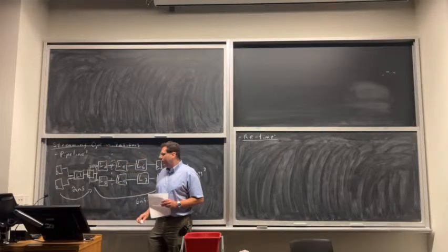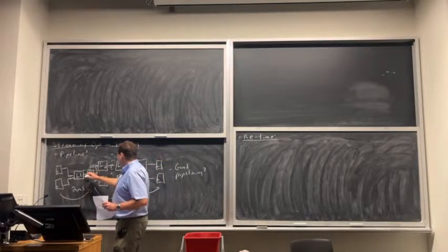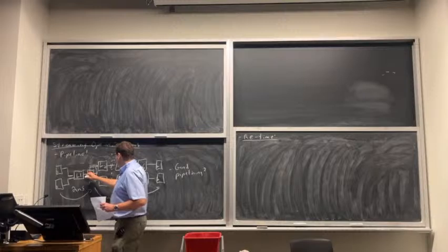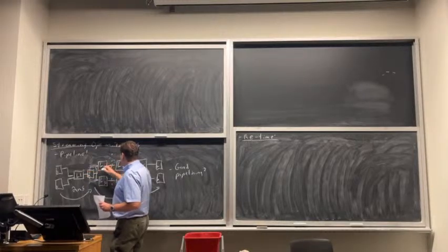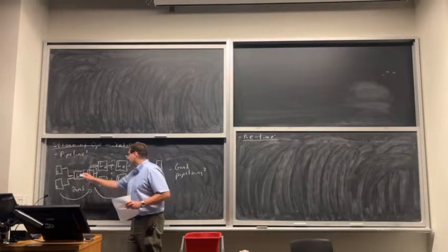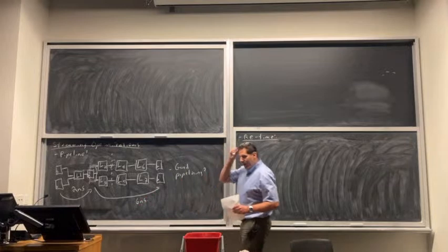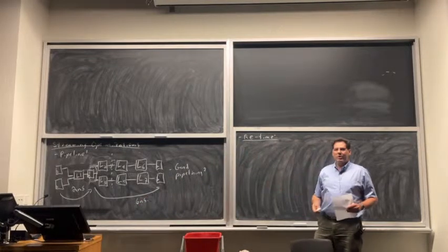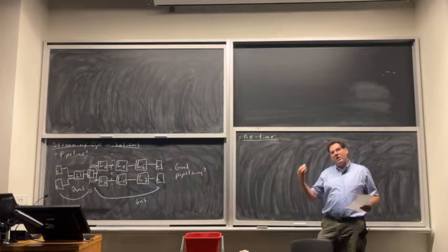And that will preserve the latency of all the paths. And this is actually invisible to the end user. Not only is your behavior at the inputs and outputs of this design unchanged, the latency is unchanged too. Everything will come out exactly on the same clock edge it used to. So that is something the CAD tool can do automatically because it cannot break your design.